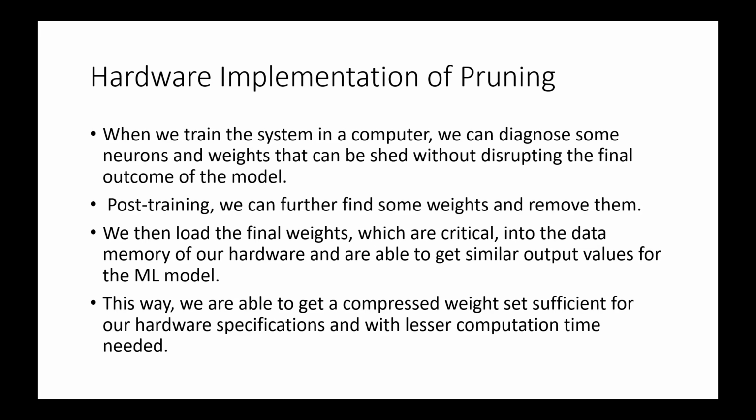Similarly, after training, we can again look at some weights which do not have much impact on our model and try to remove those weights. Then, with the reduced number of weights, we load them into the data memory of our hardware for testing the ML algorithm in our hardware system. This way, we compress the weights sufficiently for our hardware specs, and it also gives a much lower computation time for our model, which is crucial in terms of edge computation.